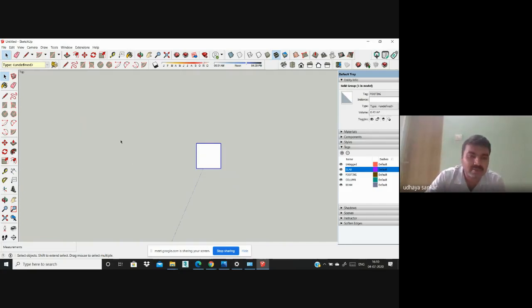I need another footing. How do we draw the straight lines? Directly go to the Tape Measure tool and click it. I take the starting point and draw this line. Now you see it automatically draws the 2 lines. This is one footing.